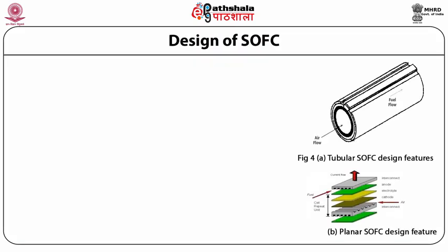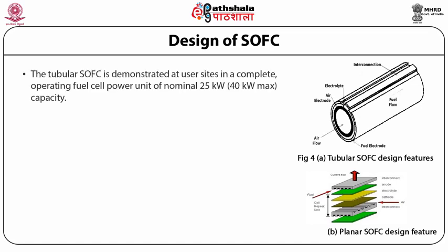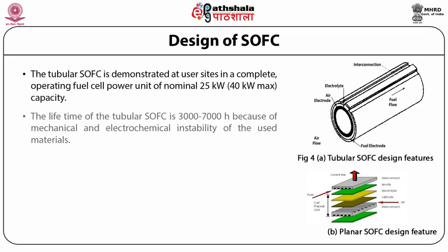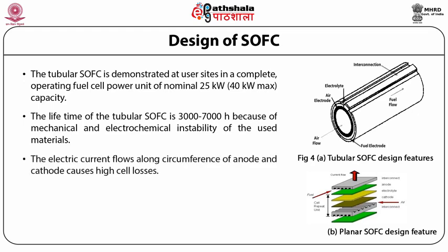Design of SOFCs. First is the tubular SOFC. The lifetime of tubular SOFCs is 3000 to 7000 hours because of mechanical and electrochemical instability of the materials used. The electric current flows along the circumference of anode and cathode, which causes high cell losses.